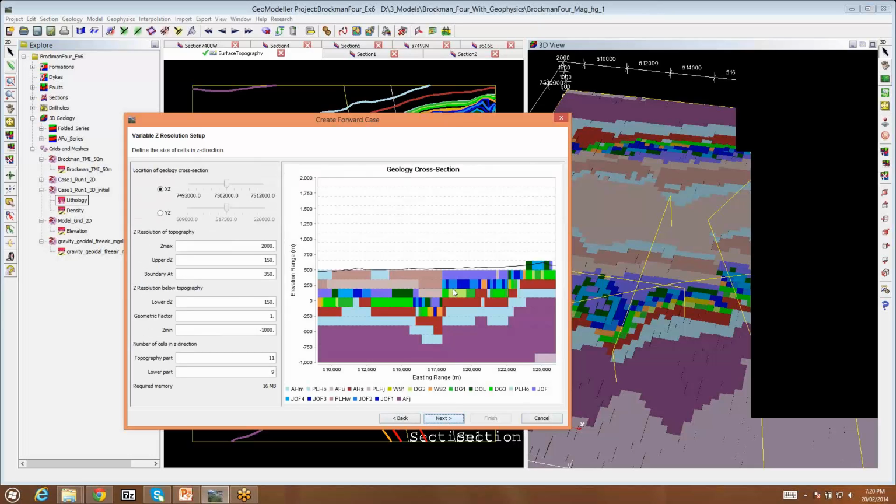So what you have here is the ability to set up a band, and the top 3 cells here are letting us set up a band where we can have high resolution in our discretization scheme. And below that we'll just have what was existing before. Also, this is just talking to the Z dimension. On the previous page we set up the X and the Y, and now we're setting up Z.